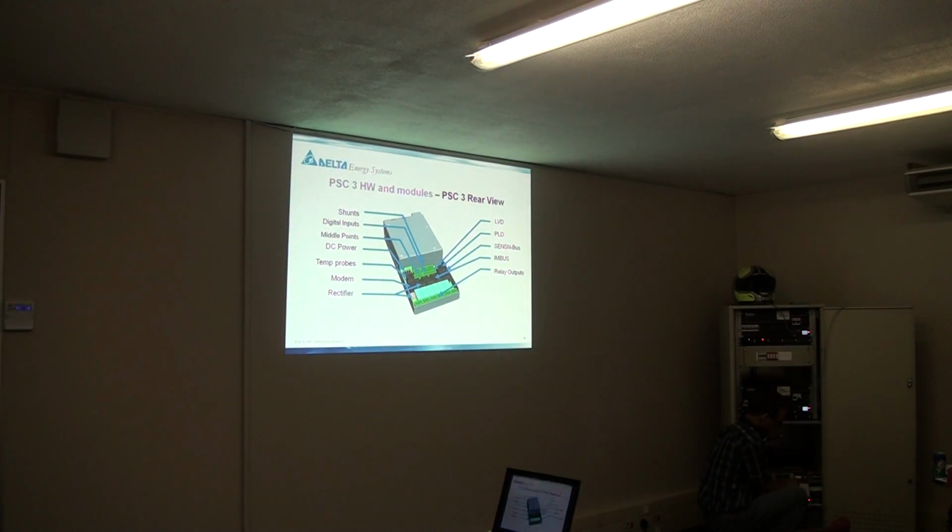So if you pull it out, everything is there: out 1, out 2, out 3. There's the rectifier interfaces, that little cable. There's our relays. That's modem. That's rectifier. That's in bus 1, in bus 2, sense in, if you have a sense in card. Open collector outputs, the 4 of them are there. LVD, the 4 inputs, the 4 shunt inputs, which you can also use as inputs. Shunt 1, shunt 2, shunt 3. So it's all there, it's clearly marked. I mean the power and the system voltage selection.